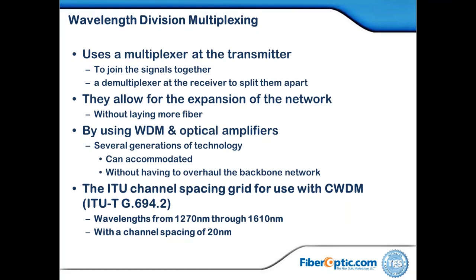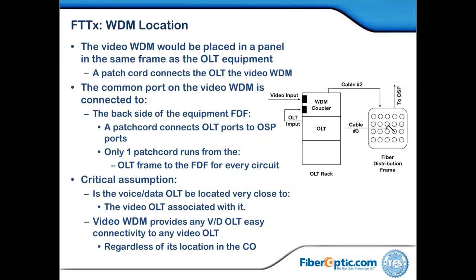that means if I'm troubleshooting one house and trying to test upstream through the splitter, my OTDR can interfere with other subscribers, say downstream video signals. Okay, so how you test this is important, and what you test it with is important. And this just shows a WDM location.